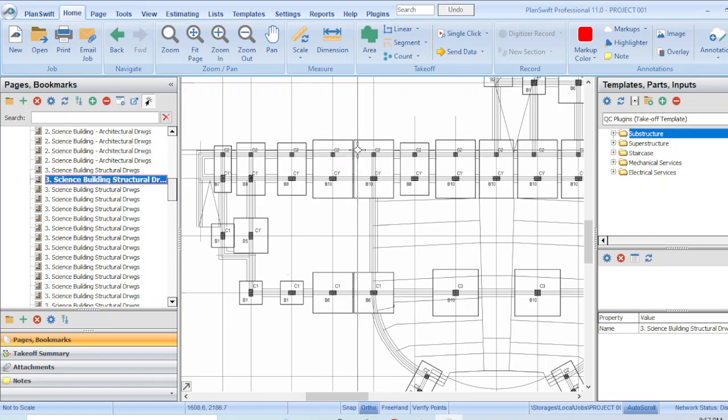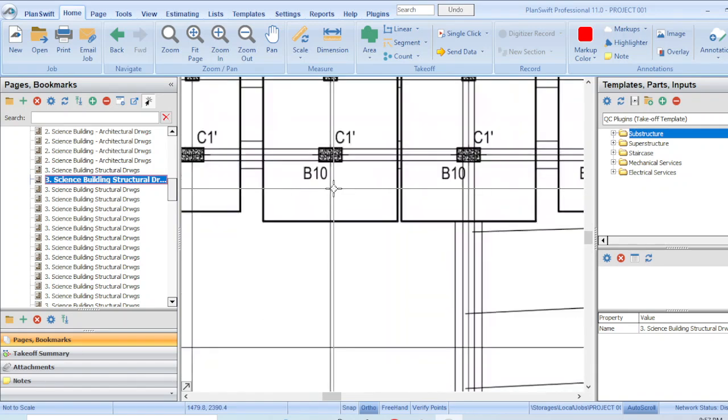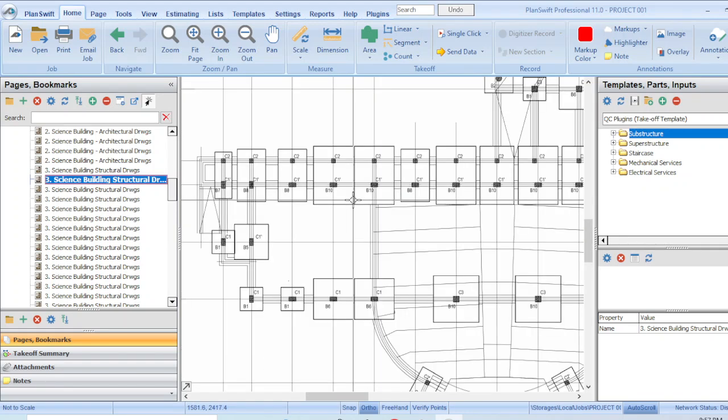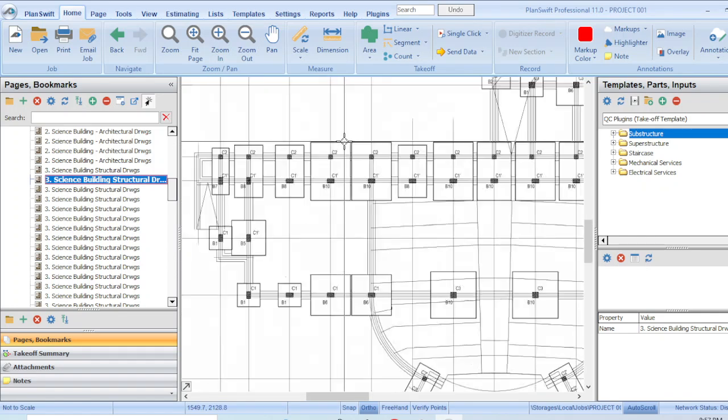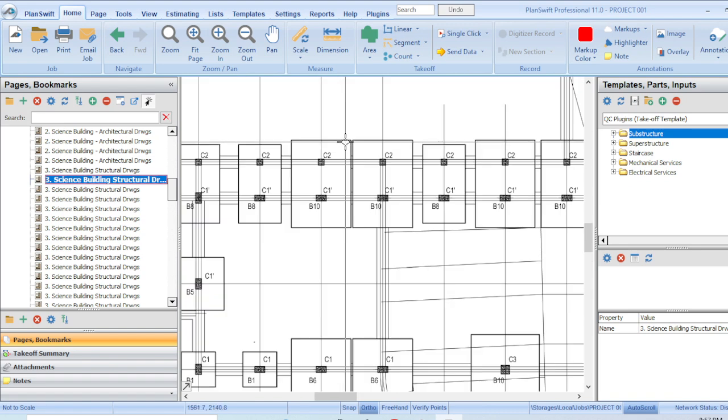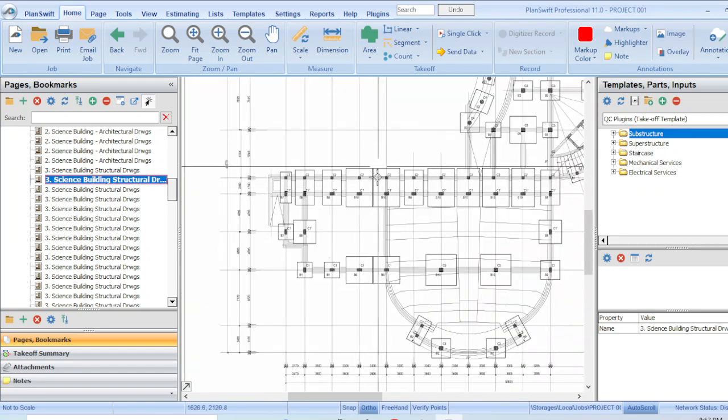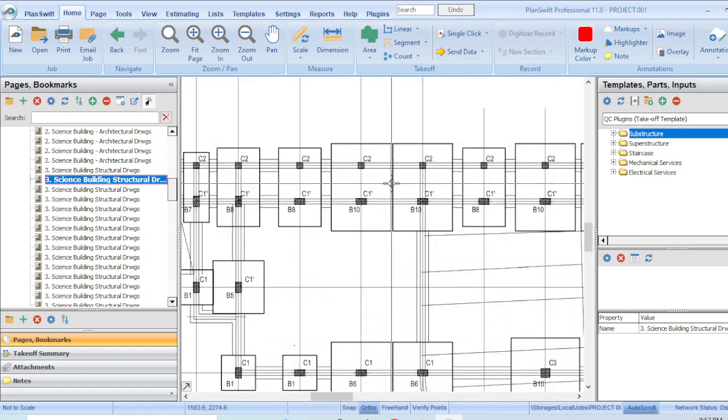Obviously, the column bases are reinforced. So during excavation, we have to add working space allowance, and as per SMM, the standard method of measurement that we use, if the face that is going to receive formwork is not above 1 meter, the working space allowance from each side is 0.3 meter. Let me show you an example.